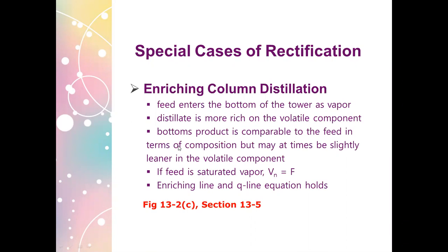If feed is saturated vapor in this case, the V sub N is equal to the feed. That is the vapor that leaves the nth plate, in terms of characteristics this time comparable to that of the feed. Enriching line and Q line equations in this case still holds.